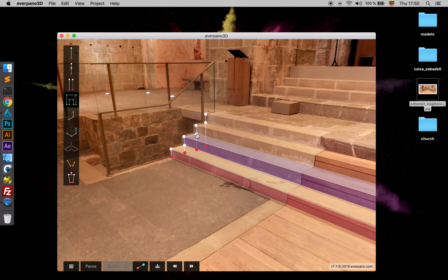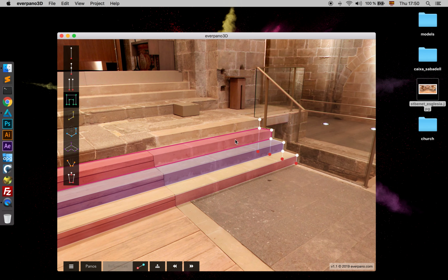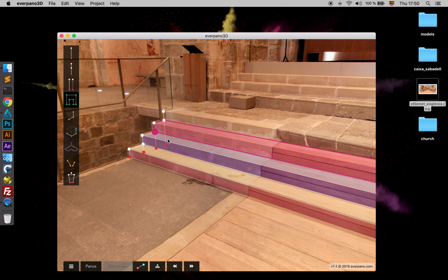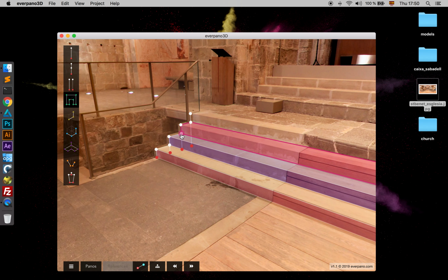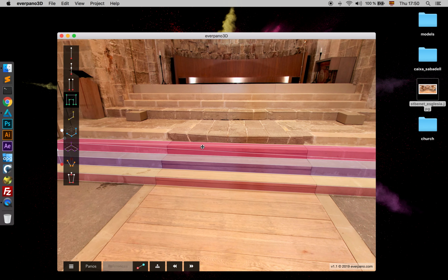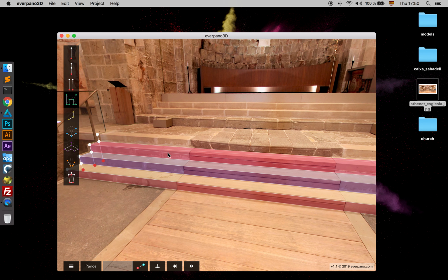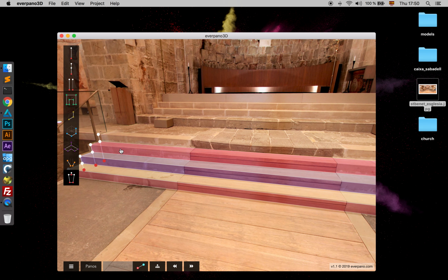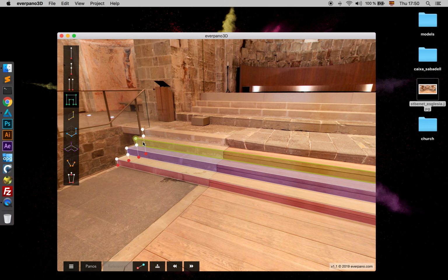And you need to go face by face and not just make only one, because when you do it like this, it doesn't know exactly how to triangulate. So, for example, it has decided to make that vertex around here, so that would have a wrong shape. So we just press delete and we make it face by face.